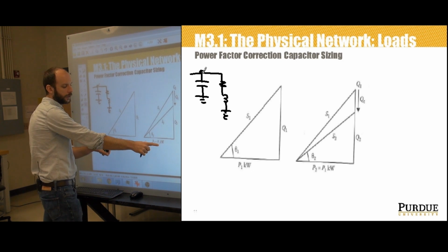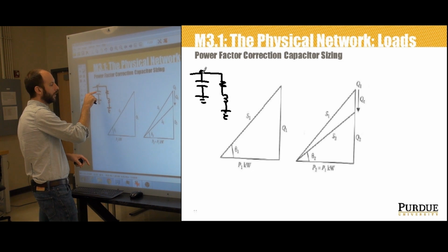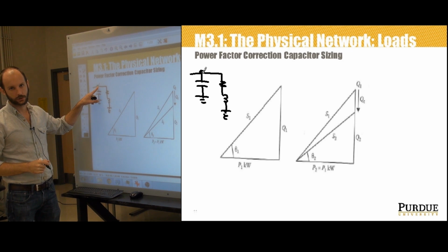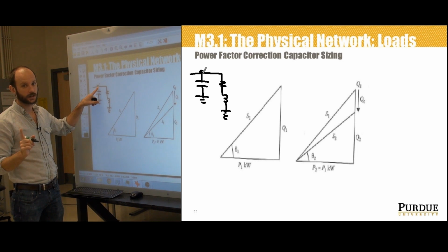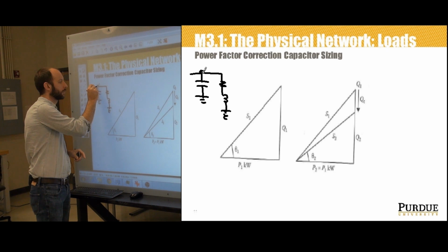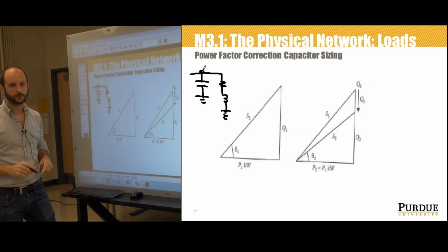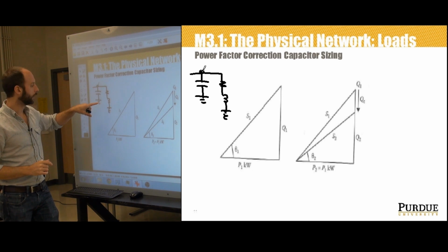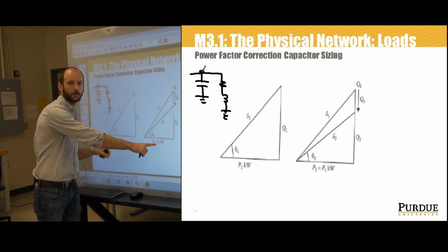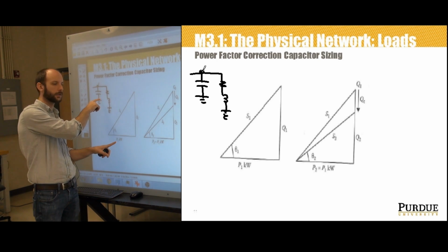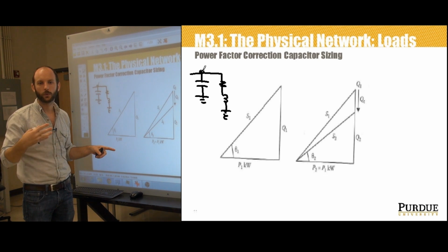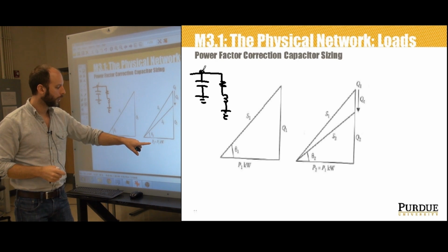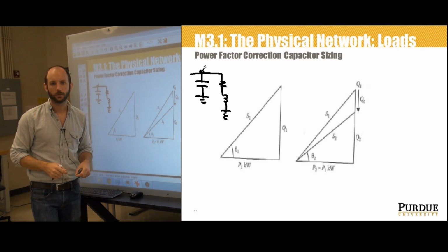There cannot be a change in real power if all we do is add a reactive element and that voltage remains unchanged. That's a key point. That voltage has to remain unchanged. Assuming that voltage is constant, addition of this element can't change P. Inductors and capacitors don't consume real power. So the real power in both cases is exactly the same. P old equals P new.